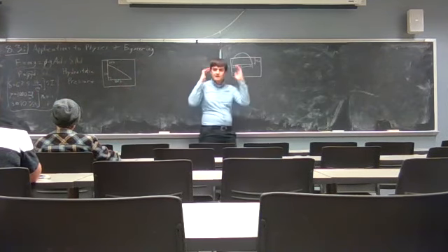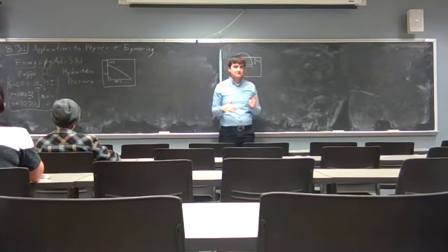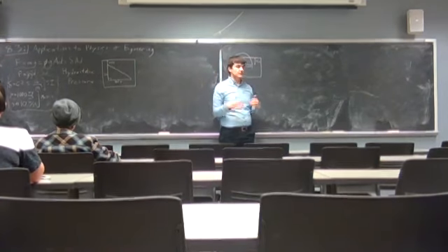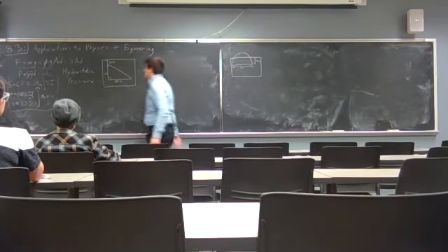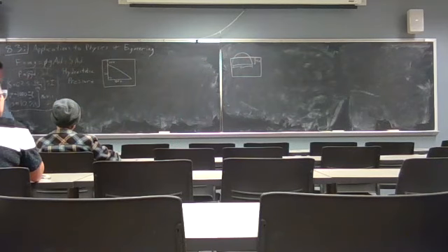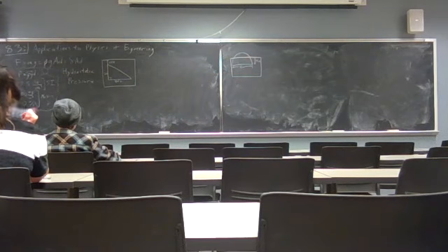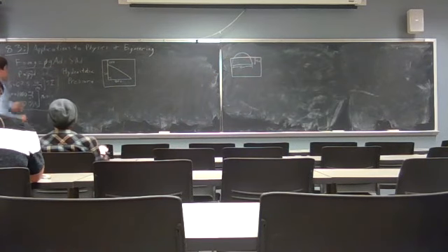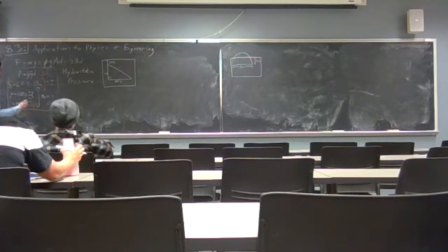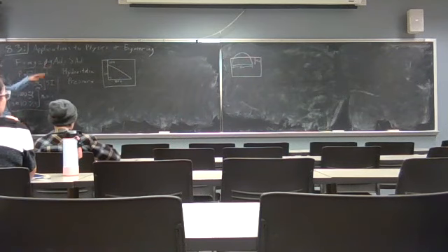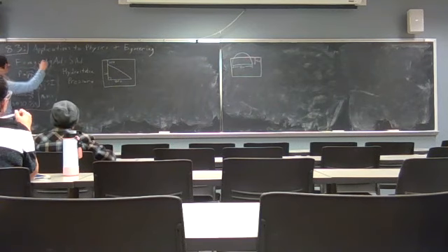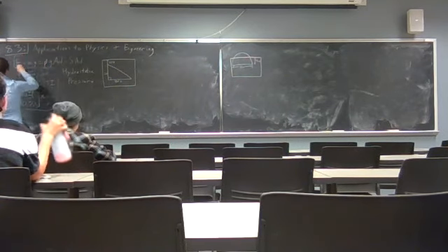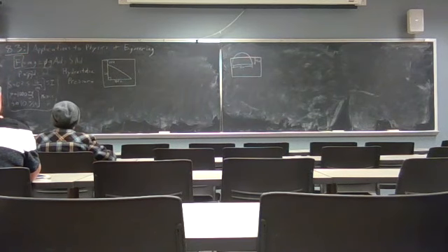It's going to have the same area always as you move down, but how deep you go does affect how great the force is. The deeper you are in the water, the greater your force is going to be. The pressure here is rho g d. That's where the hydrostatic pressure part comes in, where we find the area and multiply it by this pressure. Finding this force is ultimately what we're going to be calculating here.